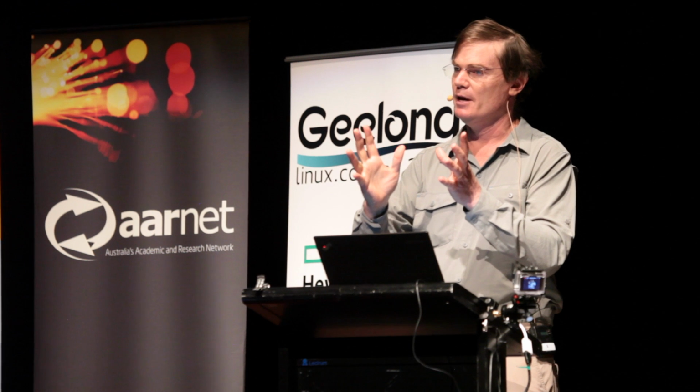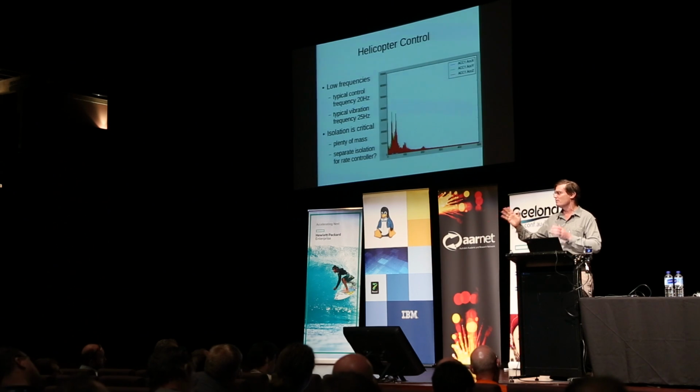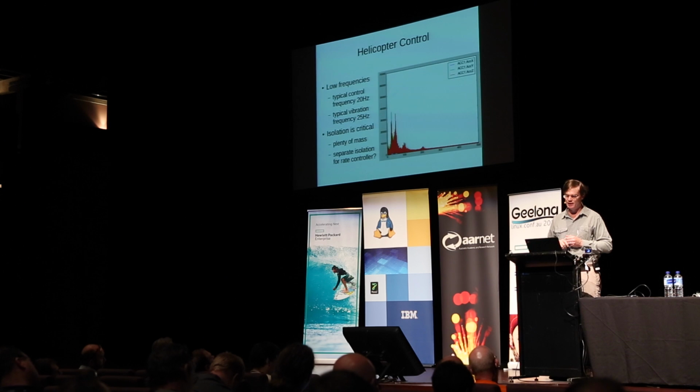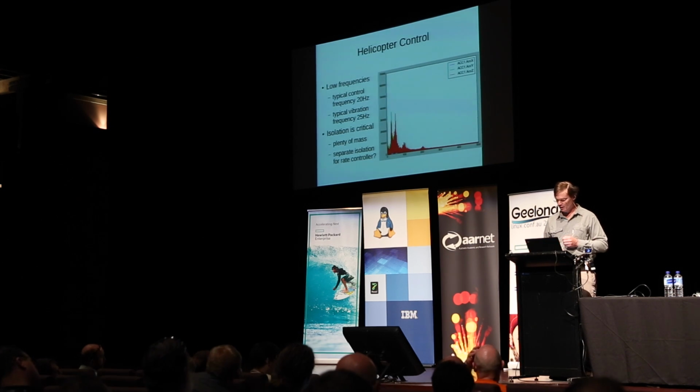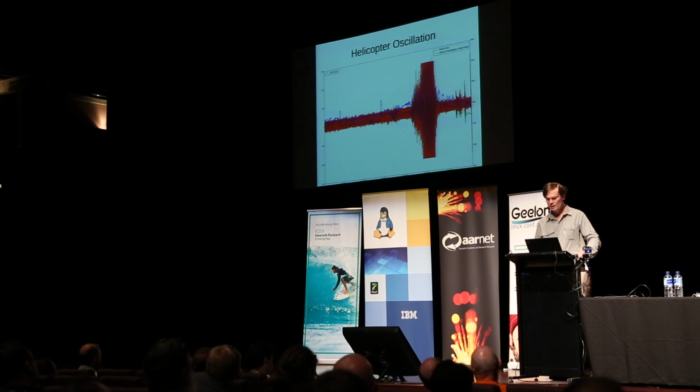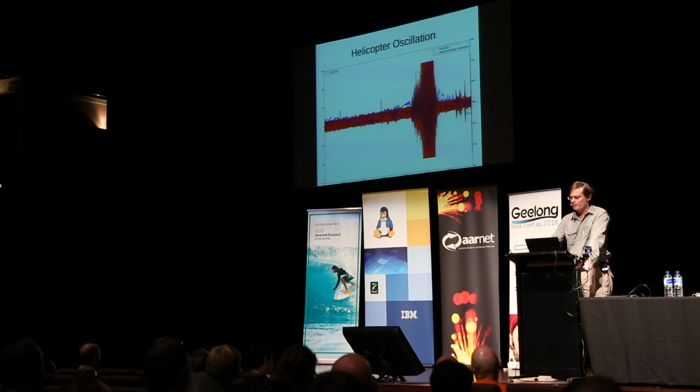So this is where helicopters get really hard, particularly as they scale up. The smaller helicopters, the frequency and the rotation rate of the blades is much higher. That might be 30, 40 hertz, giving you a bit of a gap between your control frequency and the vibration. So what problems does this cause? So this is a graph of a flight which was less than successful.